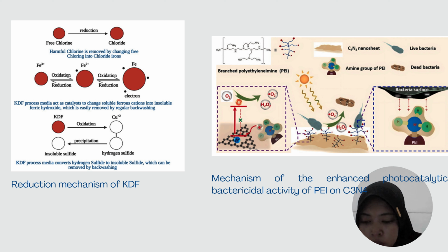To enhance the effectiveness of multilayer filters in reducing chemical and biological contaminants in surface water treatment, KDF could be added to the multilayer filters. This KDF layer may consist of various ratio of copper and zinc granules, which can remove soluble contaminants and heavy metals such as lead, nickel, and iron. They also evaluated the capacity of the KDF to reduce the residual free chlorine concentration and certain biological species in water.